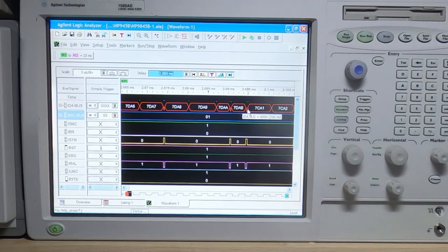We saw the reload signals going low on the counter, and the only place they can really come from is the state machine. So either there's a weird fault in the state machine, or there's a fault in one of the incoming data buffers and the wrong values are being fed through to the system, which is more likely, again, because we're seeing rogue characters on the screen. So that would also explain why it's doing that. So I'll relocate the camera and we'll see if we can repair this particular fault.